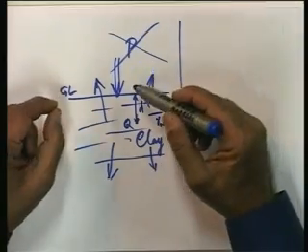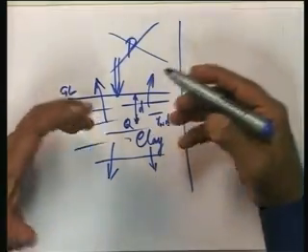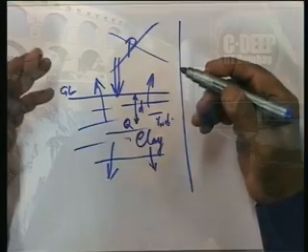Whereas, when you apply load, since the water cannot escape and since it is not deformable, it has got to resist, it has got to take up the entire load that is being applied on the soil. And because of this, water immediately goes into a mode where it experiences what is known as excess hydrostatic pressure, that is a pressure which is over and above the normal hydrostatic pressure which it is expected to experience.